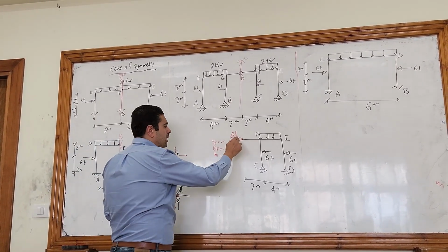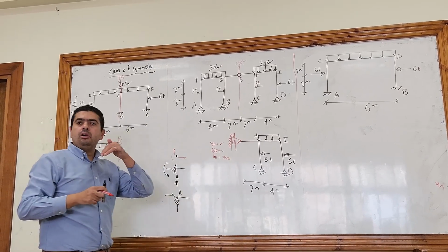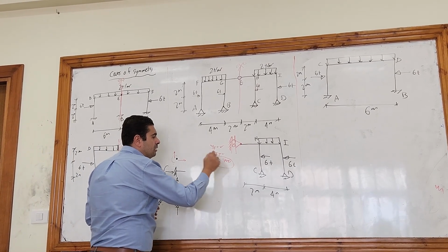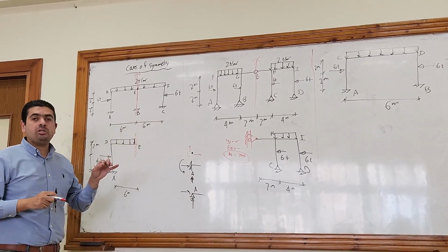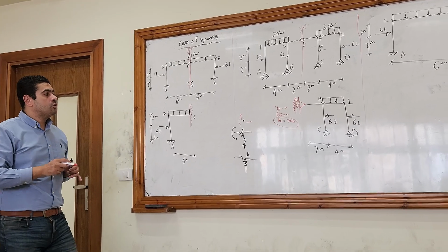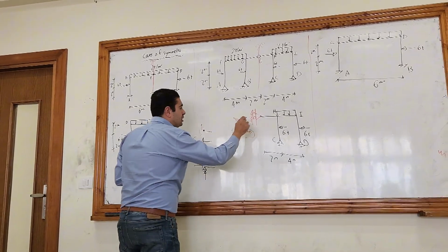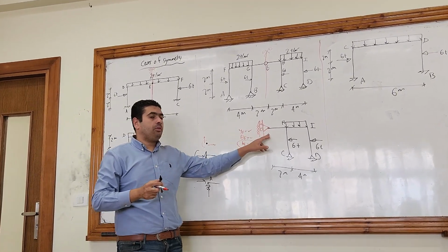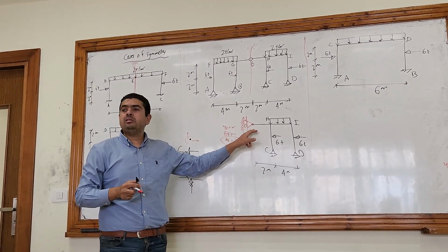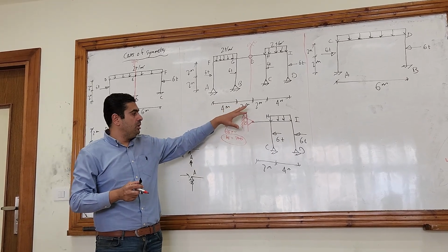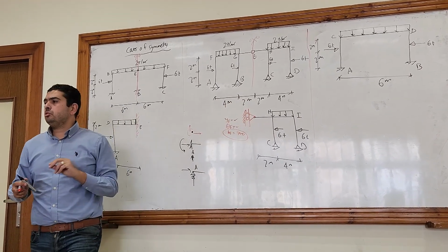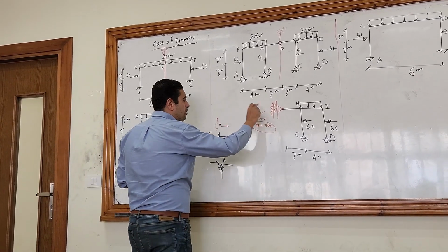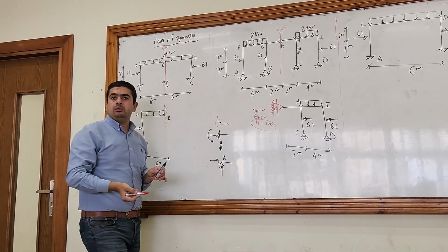If you put a hinged support, it will have both horizontal and vertical. But here, the only displacement that is equal to 0 is the horizontal displacement. So the only reaction here has to be a horizontal reaction. So that's why I thought about this kind of support, a roller support in a 90 degrees position. Okay? Again, you are not asked in the exam to prove it.